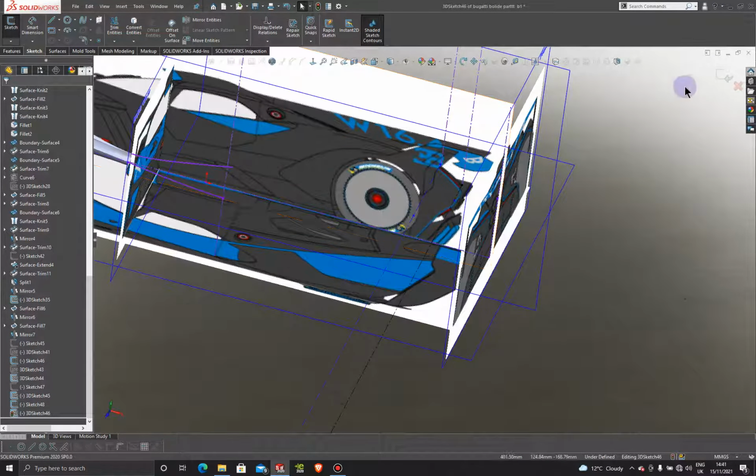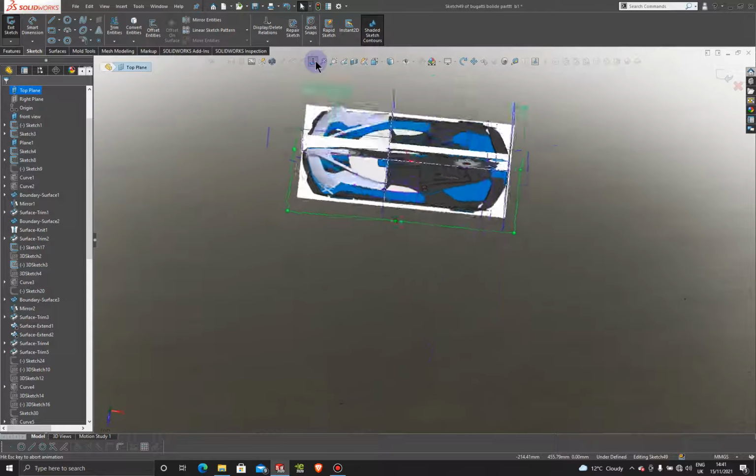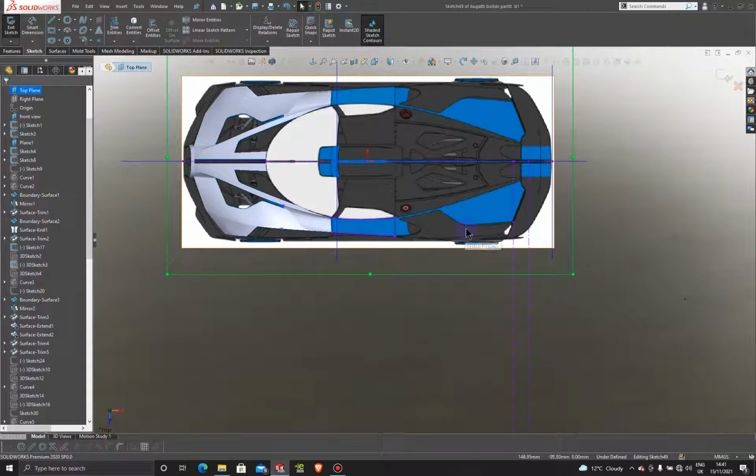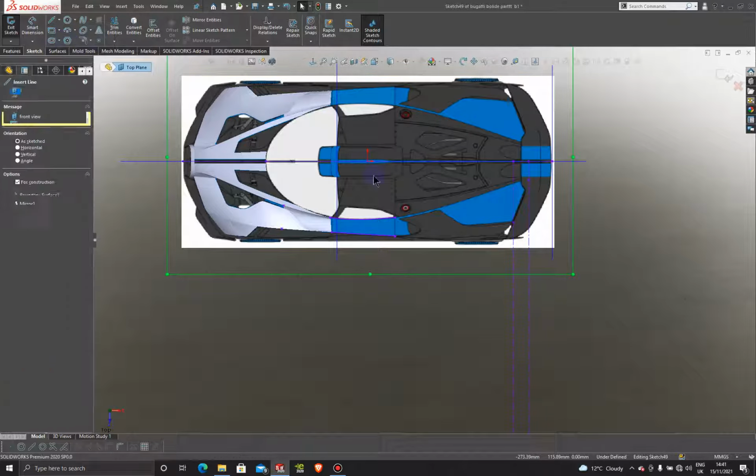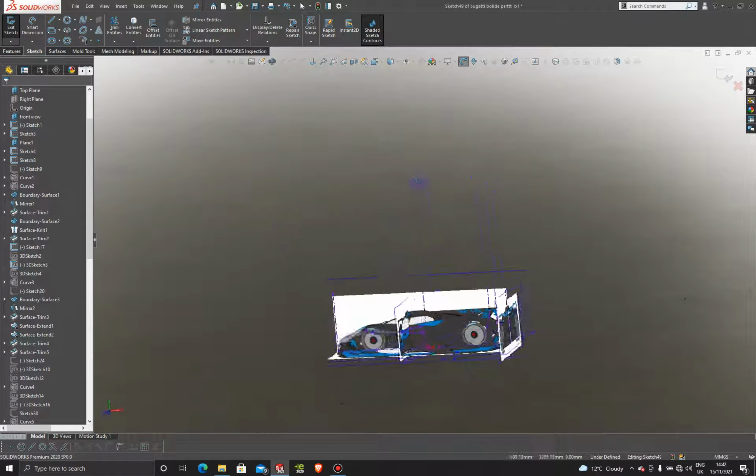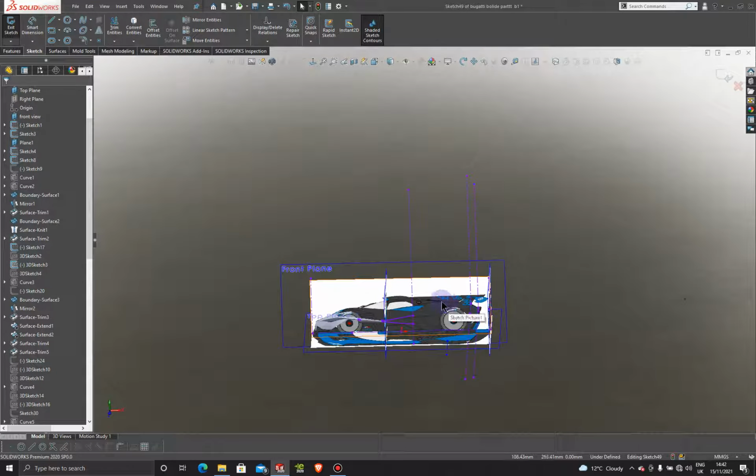And then we're going to need a second scaffold. So let's make a sketch on this top plane here, normal to profile. And we want to have this corner showing on the front axis, but we won't be able to see where that lines up unless we build this one. So it's kind of a little helper. So let's drop it into this corner here. That's one. Exit. And then, basically we won't be able to see where we need to stop that surface, right?